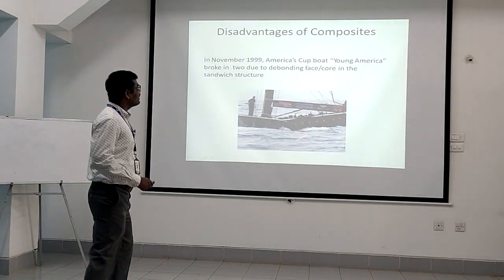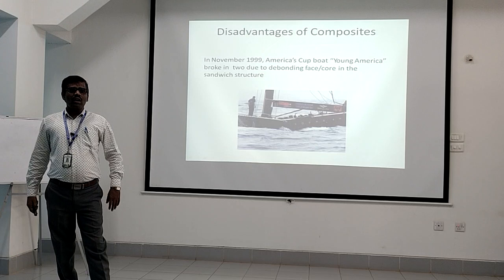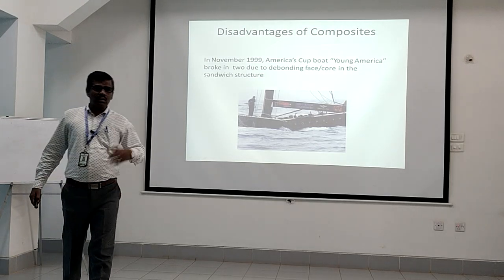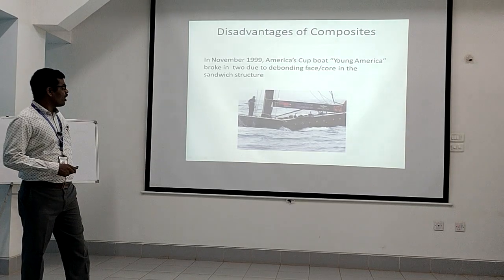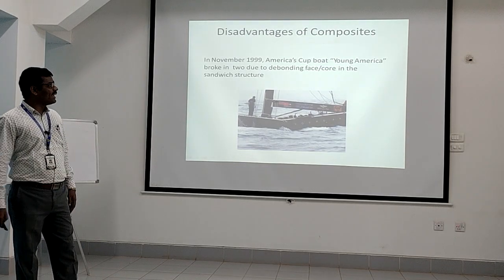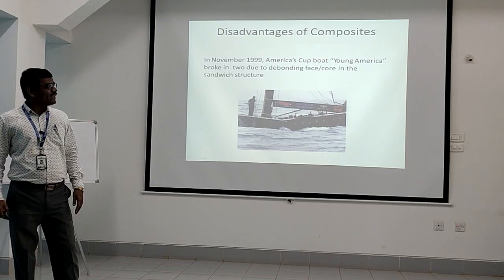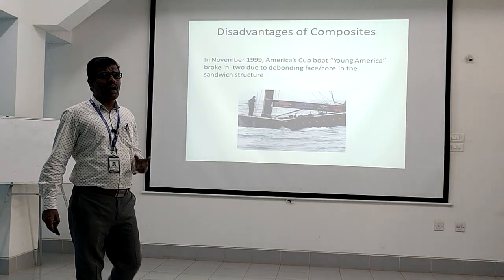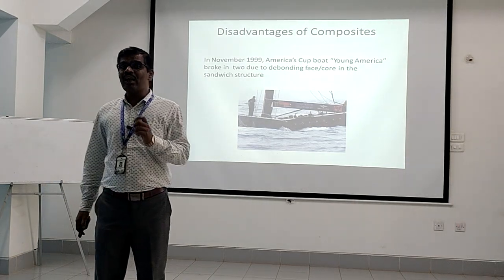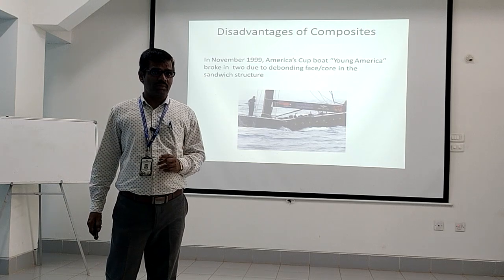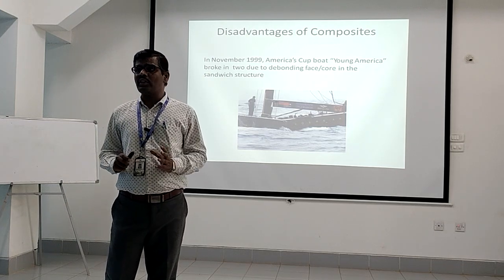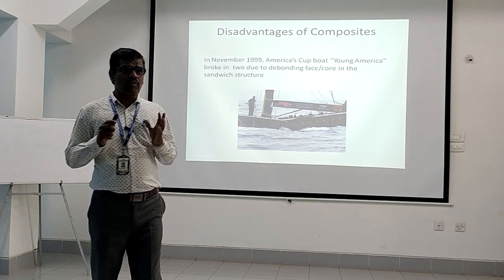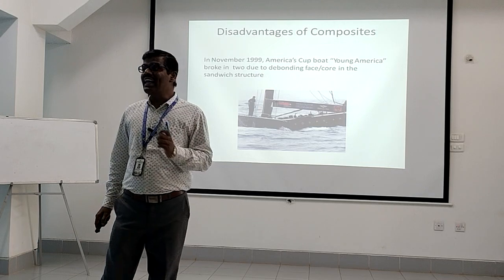So here I have taken an example where the component failed because of the debonding process. In November 1999, for the America's Cup, they developed the Young America boat. While developing the Young America boat, they used a sandwich structure. But that boat failed due to debonding.